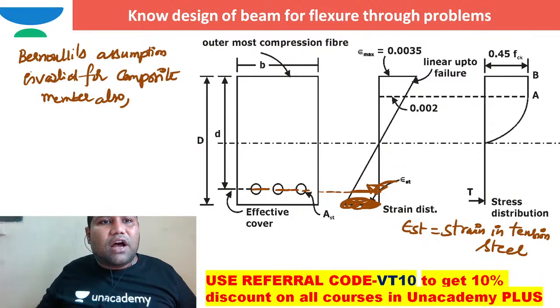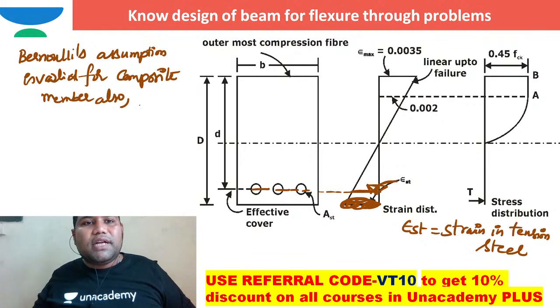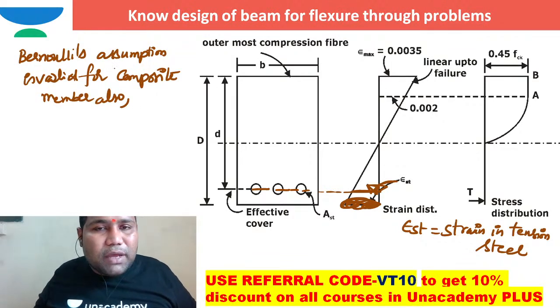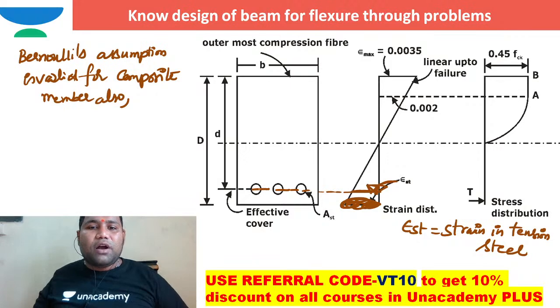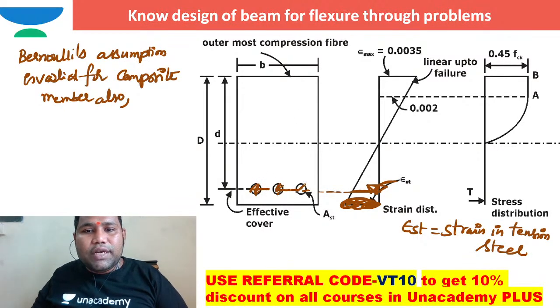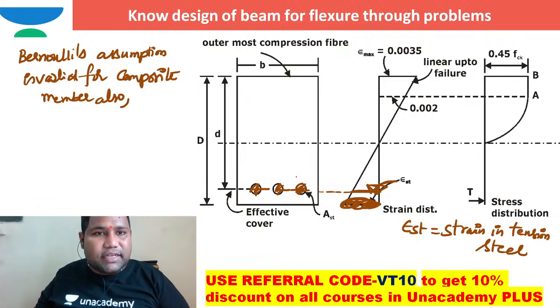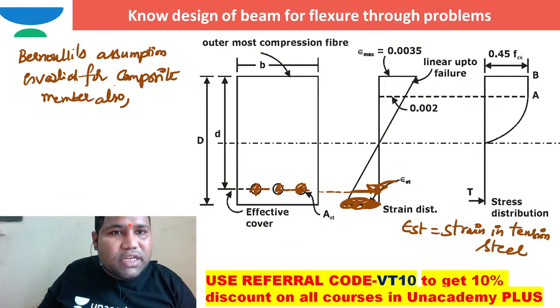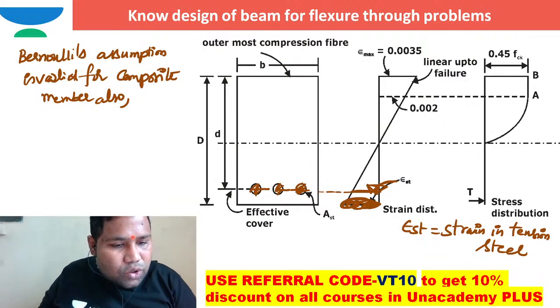As this is applicable even for composite members, that's the reason why we are using Euler-Bernoulli's theorem even for RCC structure, because an RCC structure is composed of two materials. One is concrete and the second one is steel. So it is actually a composite member.